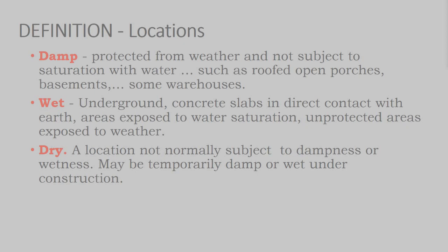Or inverters stored out on a job site with a tarp over them, and they're a NEMA 4 inverter, but then something goes wrong with the construction of the ground mount array. The material sits outside. It rains a while. Humidity gets under the tarp and into the box and starts deteriorating the electronics because they're not fully plugged up yet. So don't confuse it: if you're designing something for a wet environment, when it's not installed, that doesn't mean it's still rated for the wet environment. And that can be a very costly mistake.